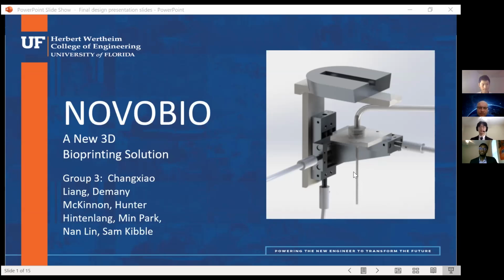To add on to what Chen said, currently for the FDR, we're producing some guidelines about where we can locate the stepper motors in order to maintain function of the flexible shafts, because there's an allowable bend radius that they can be before they stop rotating about their central axis, specified by the manufacturer. We're also going to consider not interfering with the microscope plate, etc. All right, cool, thank you.